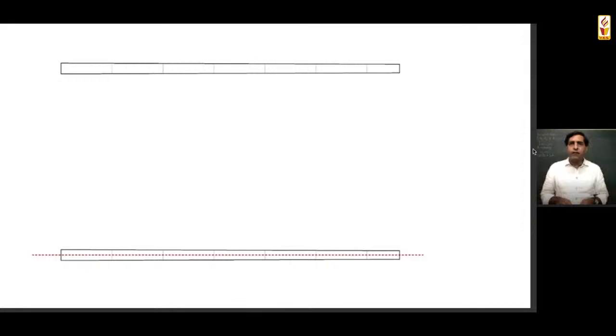Okay, so you look at these sections. This bamboo varies around 2 centimeters from top to bottom. So I have drawn a center line. Why have I drawn a center line? Like all other materials, it is important in bamboo to work only with the center line. In construction, most of the part of the bamboo should be close to the center line, because you will get bamboo which is slightly curved. But ensure that it is, as far as possible, within the center line, because if it is not, there will be some kind of extra force like bulging, which will work depending on what kind of structural use the bamboo is undergoing.